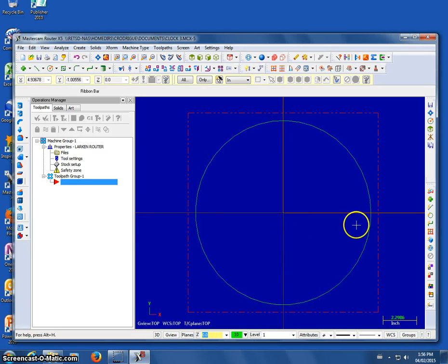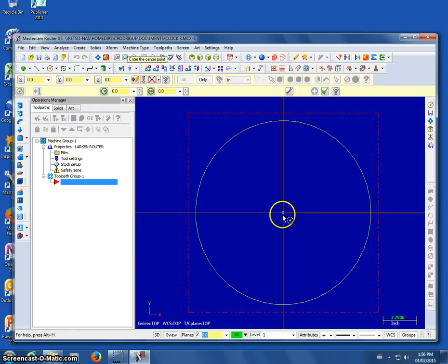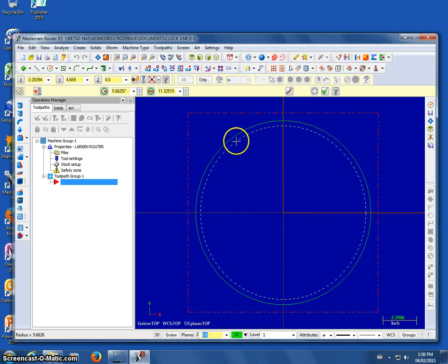This circle is going to be something we give a tool path to cut out the shape on the CNC router. But we also want to draw another circle just inside that, which will help us line up our letters, and you'll see as we go. Again, we click to that origin, it snaps in, and we draw our circle. This time I want an 11.25 inch circle, so that's 11 1/4. I'm going to click apply, see how it looks.